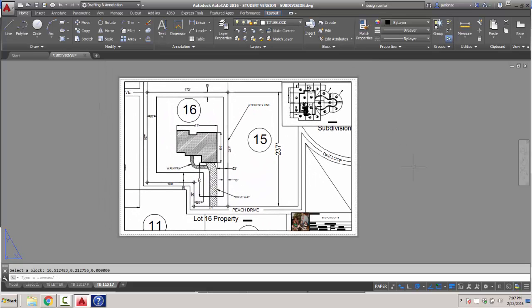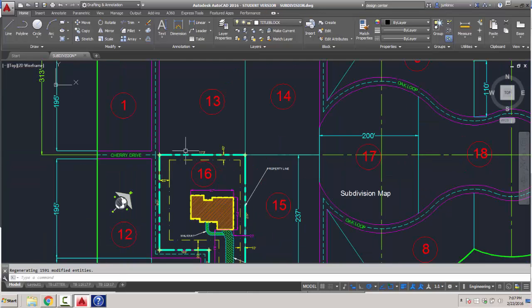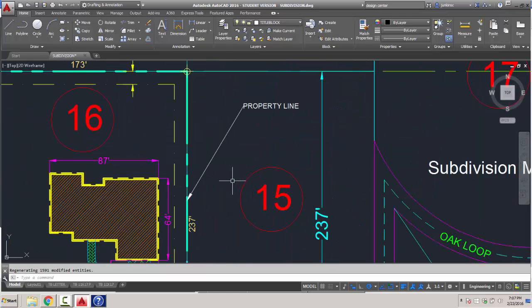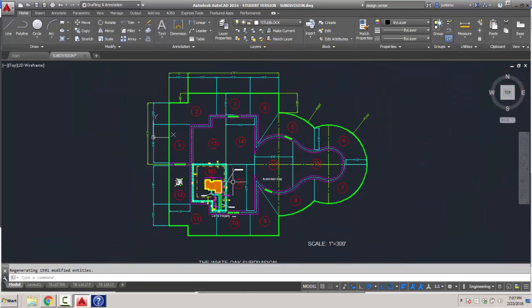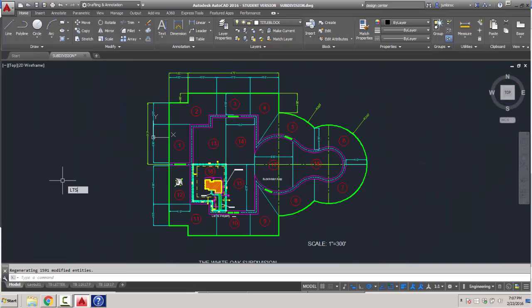So we're looking at this. Everything seems pretty good. My line styles didn't come out, so let's go back to our model. Remember how this happened to us before. Actually it should be okay because it's a line on top of a line. But let's just type in LTSCALE.